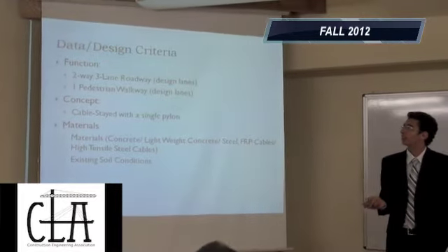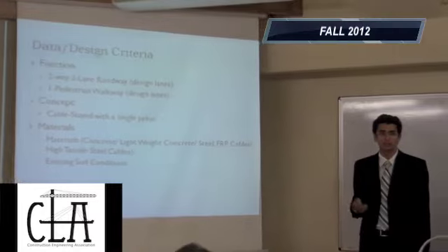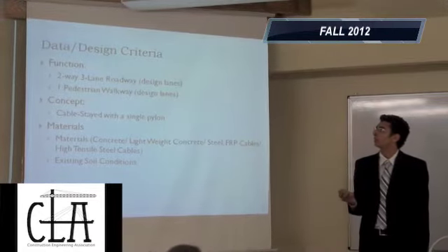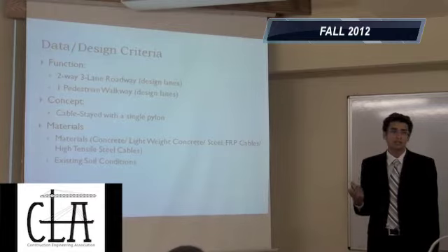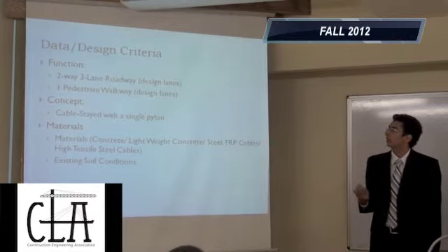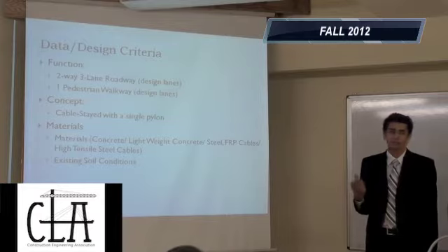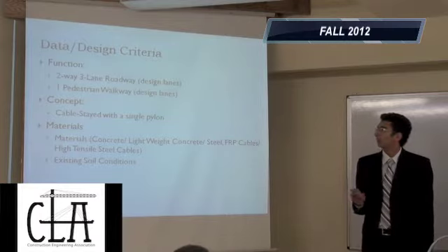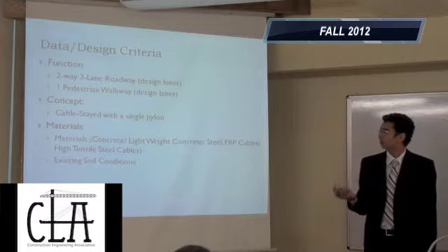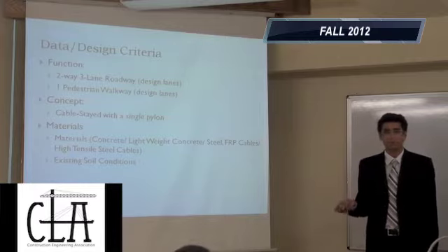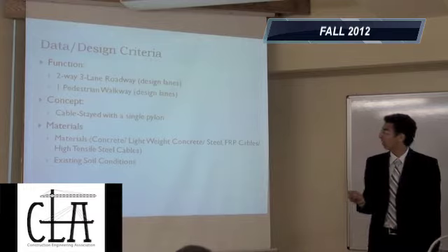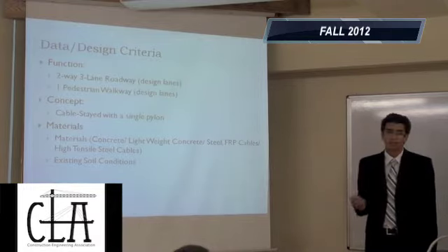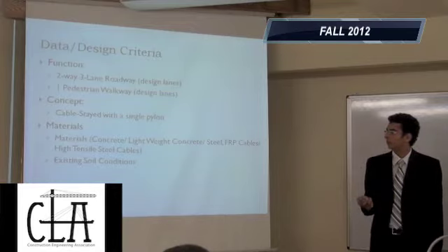Besides satisfying the basic design criteria, which are serviceability, economy, and safety, we have to have a two-way, three-lane roadway and one pedestrian lane in the middle of the bridge. It has to be cable-stayed with a single pylon without back stays. The proposed materials are concrete for the pylon, lightweight concrete or steel for the deck, and for the cables, FRP or high-strength steel cables. And we have to satisfy the existing soil conditions.